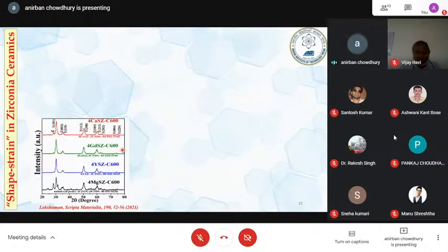So this time we're doing the same method, and what we did is magnesia, yttria, gadolinia, and calcia, all 4 mole percent. We made the powders. What we saw is that in the magnesia case there is a mixture of tetragonal and monoclinic phase. In gadolinia and yttria, it is fully tetragonal. In the calcia case, there is some amount of monoclinic phase coming up. Otherwise, tetragonal.